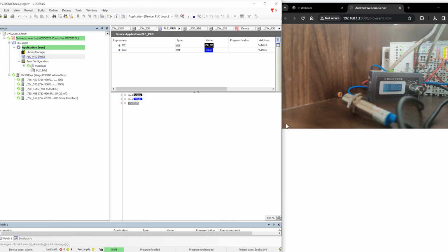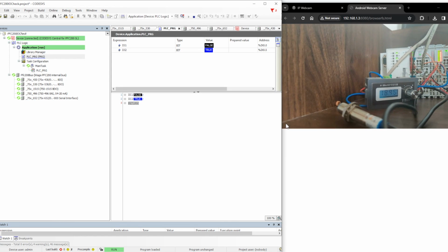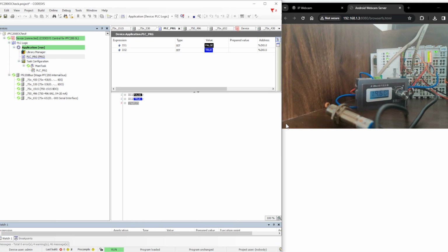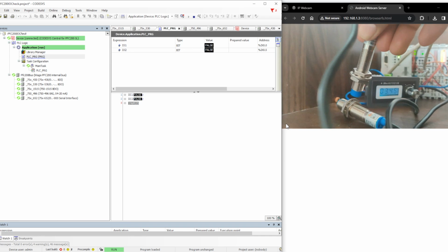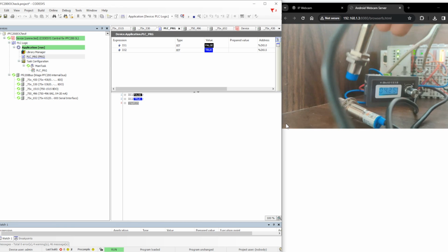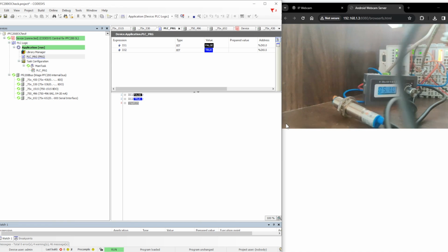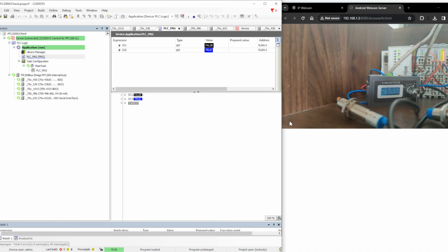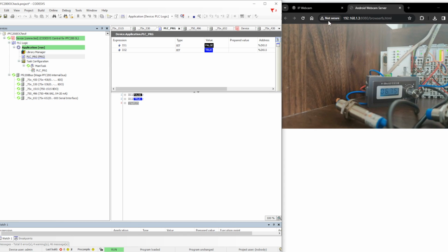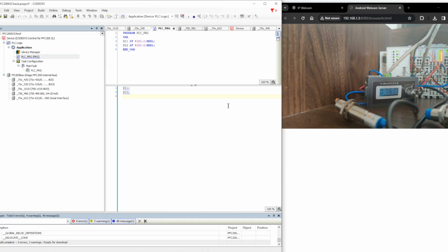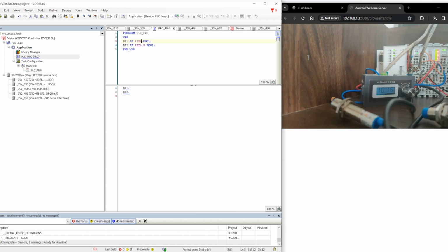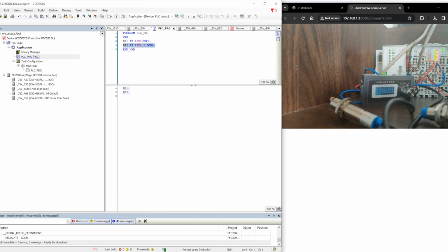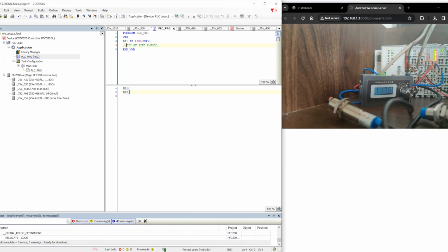So now let's see the third type, where we do not utilize the bit by bit or channel by channel address, but we will utilize the whole address. Right now, what we were doing is mapping each channel, and we were utilizing only those particular channels where I have connected the IO. If we want to utilize the full channels, then we will have a different kind of mapping. We can use the same bit by bit, but if we want to utilize one address directly, then instead of bit by bit mapping, we can go to the card and see that I have a main address as %IB, because the whole thing is a byte, and the rest are defined as boolean. So we can define that as %IB0 directly.